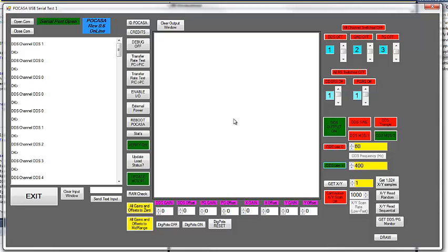Say you have a really small signal in here, you turn up your gain in X, and it would be a bigger signal here. Maybe you want to get it to fill up the whole screen so you can see it better, so you can see a little more detail. Same thing with Y. You get it to fill up the whole screen. The offset would slide it left or right or up or down. Maybe you want to get that thing centered so you can maximize the screen or maximize the input so you can see a little more detail.